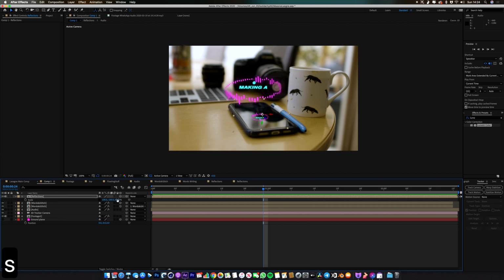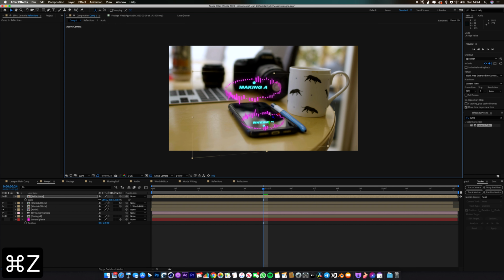Let's scale it up. Hit uniform scale on that. Because we flipped it upside down, these controls are not doing the things that we're used to them doing. I don't want to move anything on the y-axis. I don't want it to go up or down anymore because we've set the y-axis using the ground plane. But we can push this z-axis and this x-axis around just to get it in the right position.